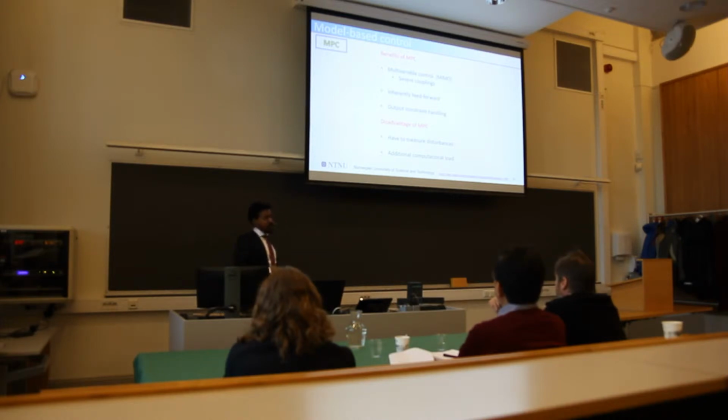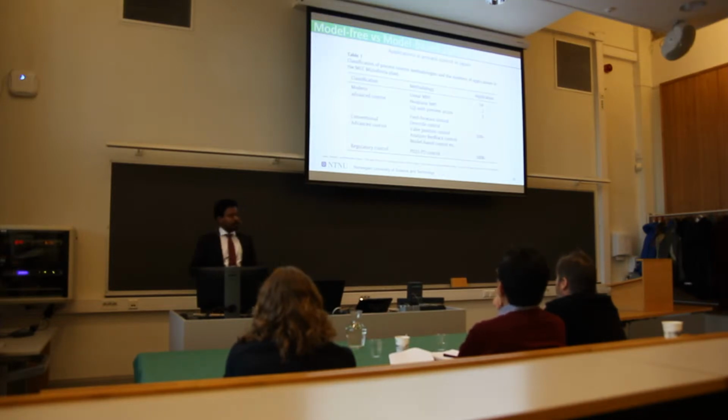You have to measure the disturbances. It takes disturbances as a feed, without which it cannot act. And also the MPC runs an optimization, so it's an additional computational load. Now, to address the main topic of this trial lecture, the comparison between model-free and model-based control. I presented some model-free methods like PIDs, and I presented some model-based control like MPCs.